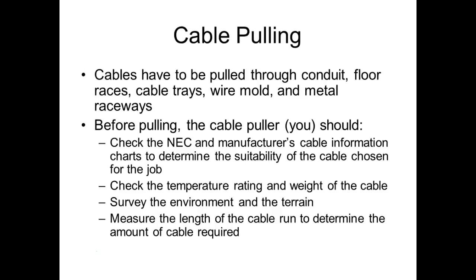And there's a lot of rules on how many conductors you can pull, how much space you gotta leave. We call them conduit fill. And we don't teach that. They would teach that in commercial wiring. Your conduit fill, what's legal, what you have to do there. So that would be a real good class today.